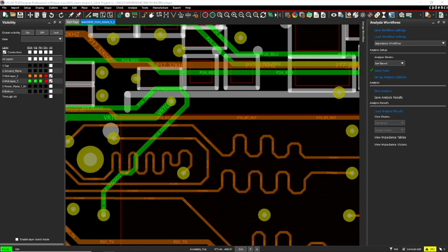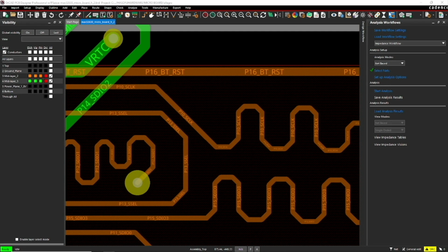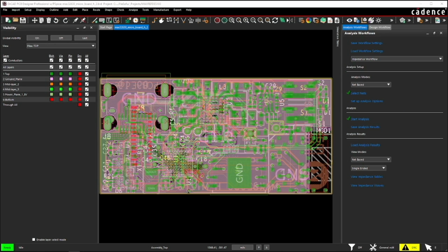But I still recommend asking the manufacturer for this information before trying to do all of that calculation alone. Then feel free to still do your own calculations to verify your own methodology and see if you get similar results as the manufacturer for the device. There's one major thing though. This meandering process and all these signal integrity and high-speed techniques are only predictable if you have a strong control of the trace impedance and the PCB stackup with the right materials. You will need to have done the calculations for controlled impedance for your materials and PCB stackup beforehand in order for these techniques to work.